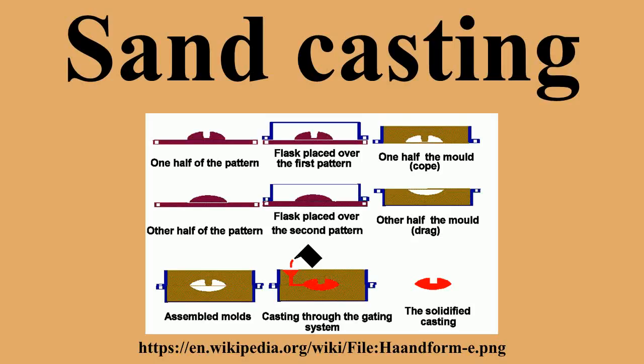The casting may be further strengthened by surface compression treatment, like shot peening, that adds resistance to tensile cracking and smooths the rough surface. And when high precision is required, various machining operations are made to finish critical areas of the casting. Examples of this would include the boring of cylinders and milling of the deck on a cast engine block.